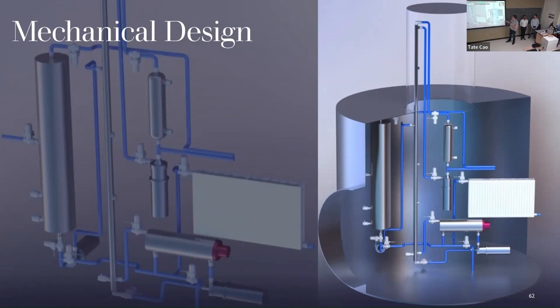As well as all of the components that we had to design, we had to pick components that were off the shelf. So we decided to go with a sealless type pump, so that it would be better for long-term use and we wouldn't have any seals that would go bad. All the off-the-shelf parts like solenoids, pumps, temperature sensors, and level sensors were picked for the environment with the heat and corrosiveness. Again, we have our rad as well. We can go through the design portion a little better later.